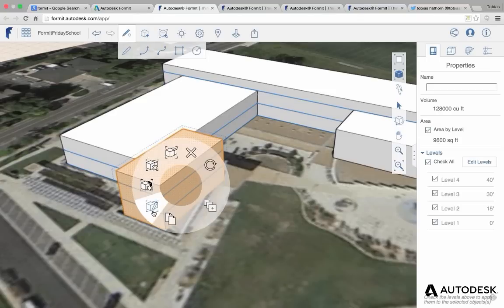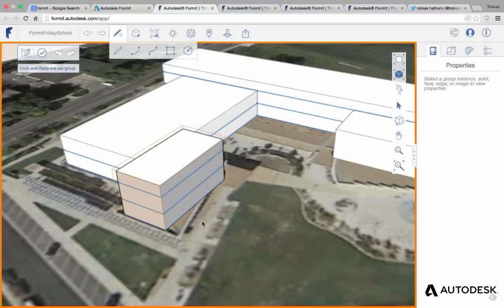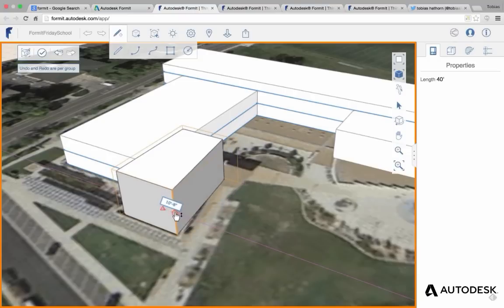All right, so we did drag face before to change. You can also do drag edge really easily in FormIt. So you just select an edge, you get the little feedback on the mouse cursor, and then you click to start a drag. And this is really helpful to use the axes to make sure you stay planar. So I'm going to go ahead and, you see as I start to wander around off of that purple axis, then I can start to make it a little bit crazy.